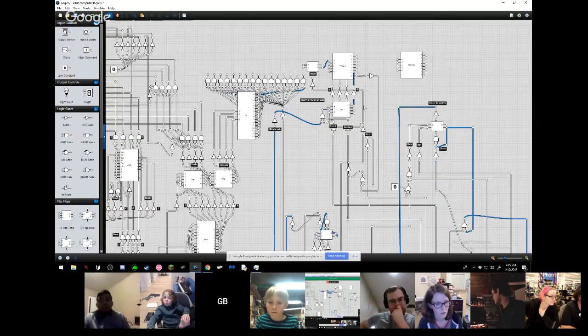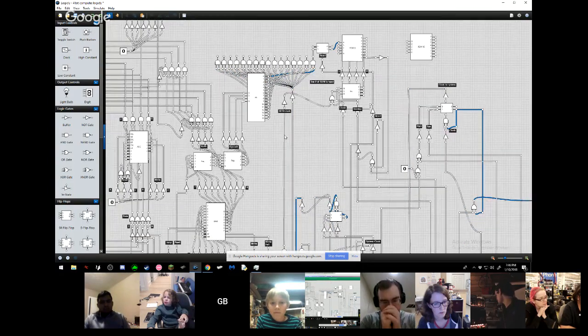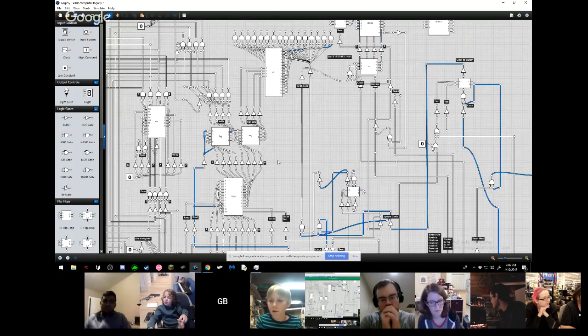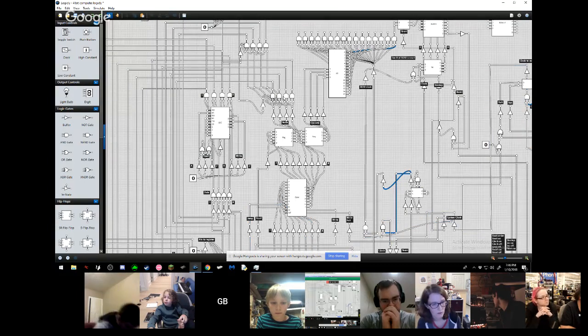It goes so fast it doesn't actually show up because it resets on the same frame that this turns on, because this is the reset line. So you can see your opcodes are coming in here. Oh, no, it's actually, yeah, the opcode is 0. I just forgot it was 0. So this is the opcode, and the value section is just staying blank because no operation doesn't need the byte.